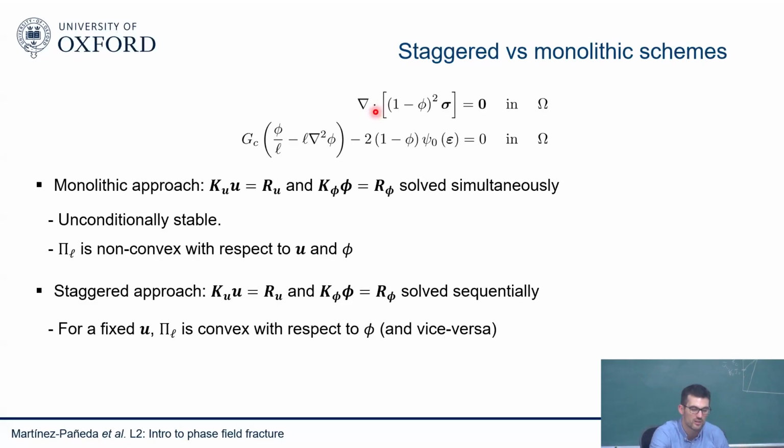If you do single pass, you could lose the unconditional stability. Single pass can be a bit more robust, you'll get convergence more easily. So if you deal with a very complicated, nasty problem where you're not getting convergence, you can use the single pass, and I don't think I've ever seen any problem where you don't get convergence with single pass, but anyway, we'll discuss that later. With single pass, you'll get convergence, but then you become kind of a forward Euler type of approach. Because you are freezing and jumping between increments, if your increment size is too big, you may be deviating from the solution. So it's kind of an explicit approach. You may have to use very tiny increments just to make sure that you're not deviating. You need to do a time sensitivity study, basically.